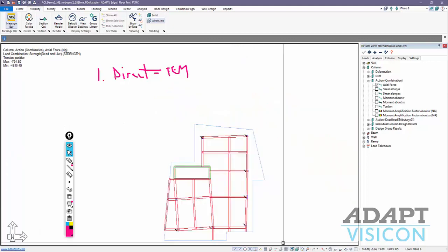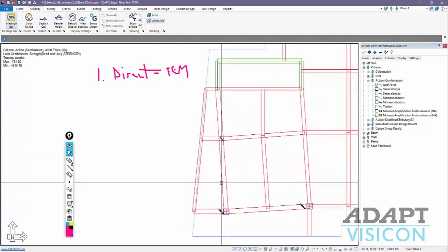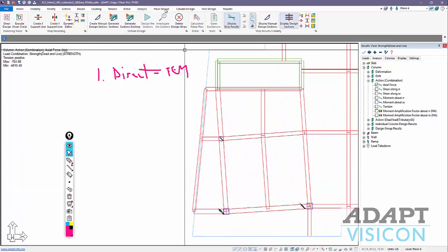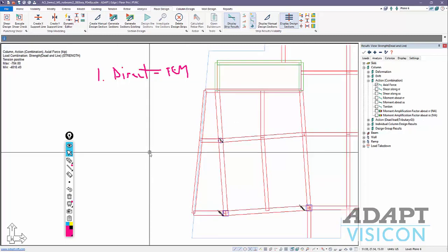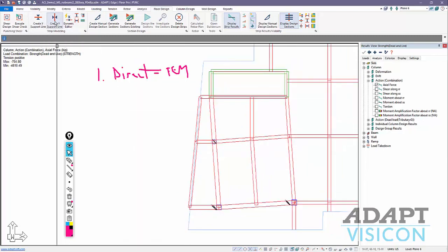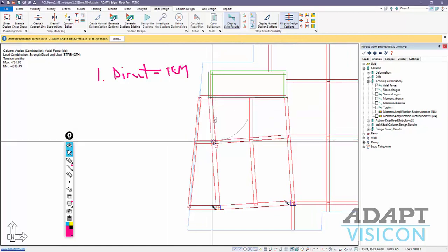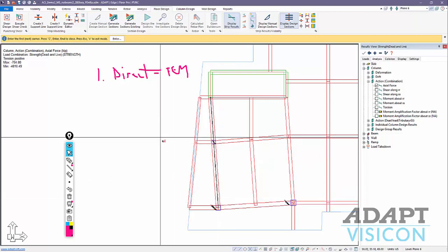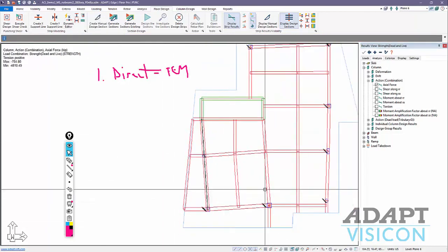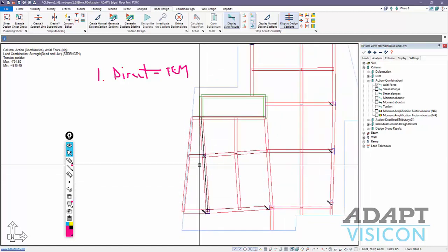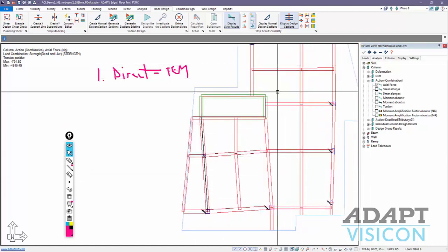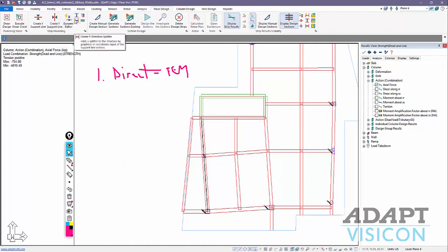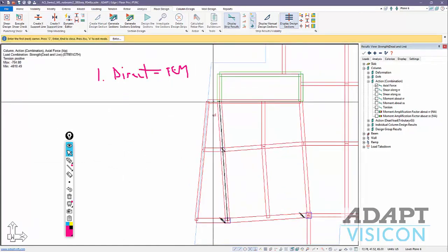So now if I take this beam and go back to floor design, I'm going to turn on the strips for this level. We may not have any strips. Let's go ahead and create a design strip. So I'll use the X direction, and we're going to go from end to end like so. And then I'm kind of isolating the beam from the rest of the slab here. Typically we would have support lines on all beams if we were to design the entire system, but here we're just isolating one. And I'll go in and I'll add a splitter.